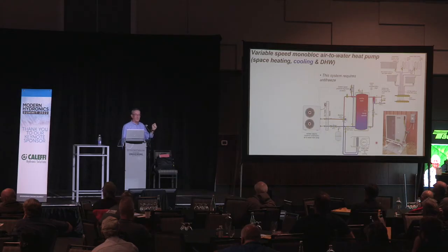So whenever a tap for hot water is open and the flow gets up to about 0.7 gallons per minute, that little switch will close. You can run the contacts from that switch right to one of your zone relays, so you aren't directly switching line voltage through it. And that simply turns on the circulator to the right side of the buffer tank right here. And that will bring hot water from the top of the buffer tank through that heat exchanger